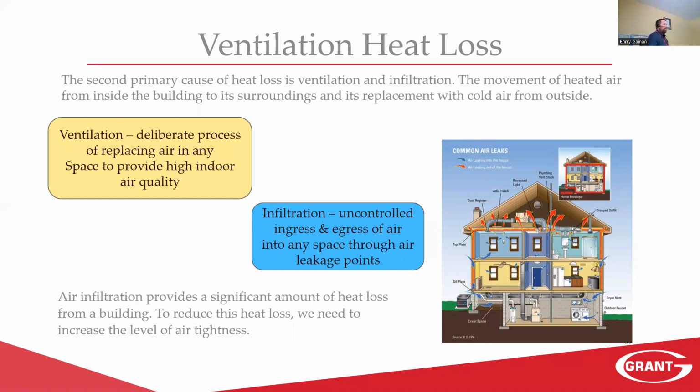The difference between the two: ventilation is the deliberate process of replacing air in any space to provide high indoor air quality, whereas infiltration is the uncontrolled ingress and egress of air into any space through air leakage points. Air infiltration provides a significant amount of heat loss from a building. So in order to reduce this, what we need to do is increase the level of air tightness.